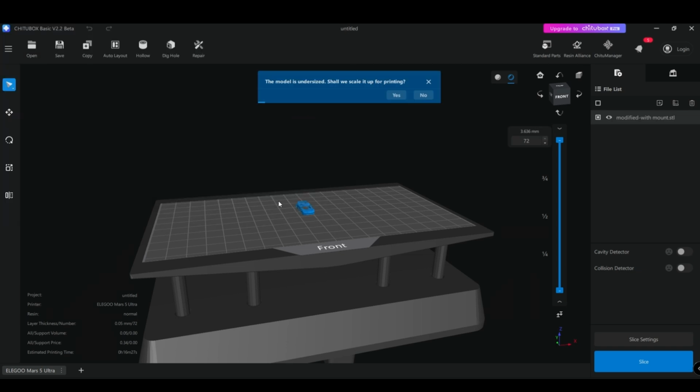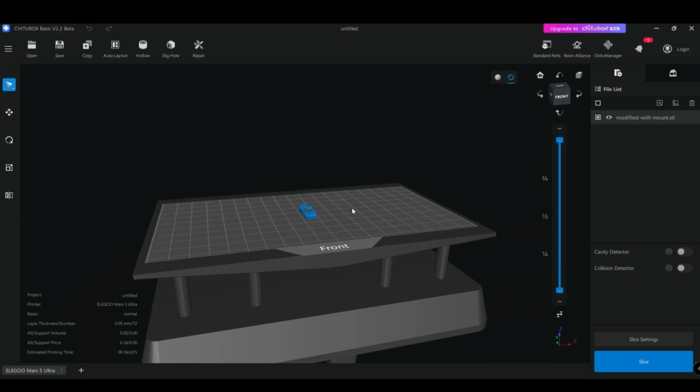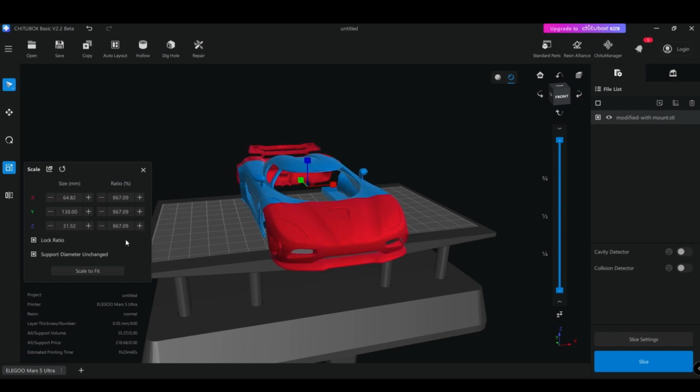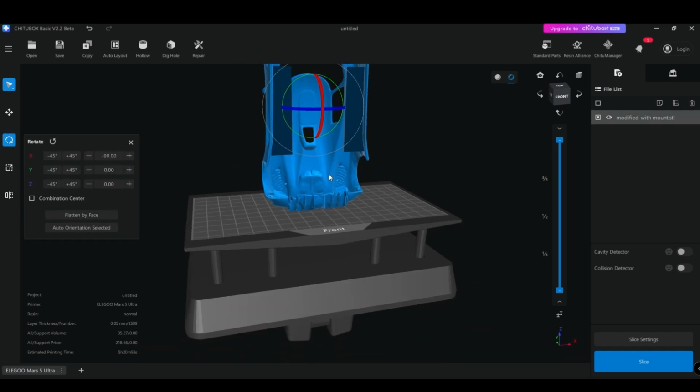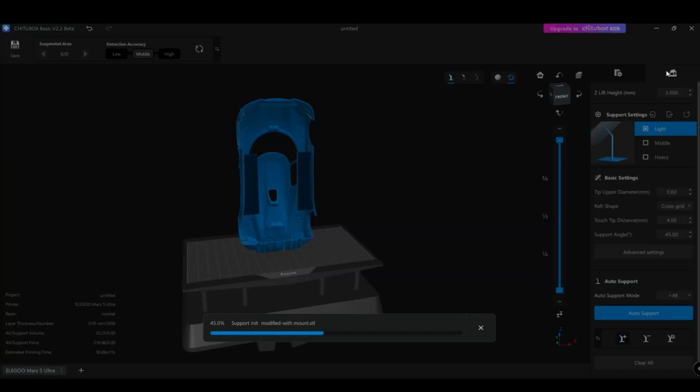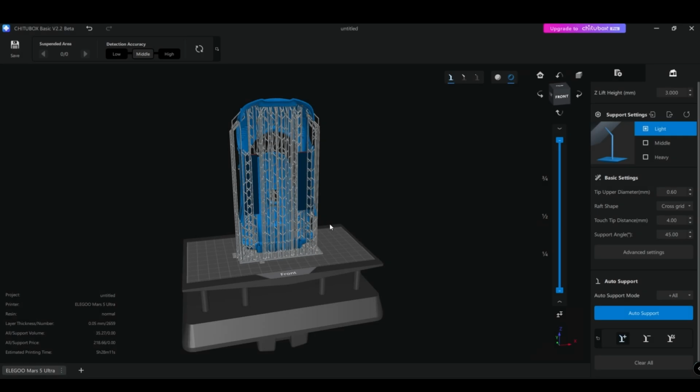My resin printer uses Chitubox, so open the application and then the file for printing. And here I have made a mistake on the scale, which I can fix later in Blender, but for now we can just increase the scale in Chitubox. Now rotate for printing. I print as vertical as this helps minimize any layer lines and has fewer supports. It does take longer to print this way.